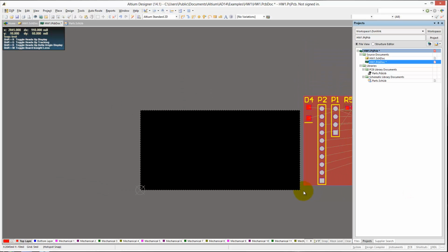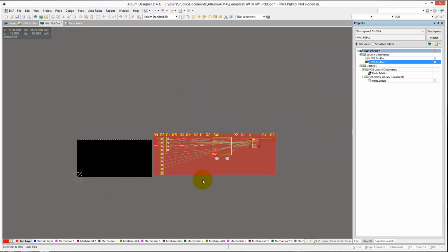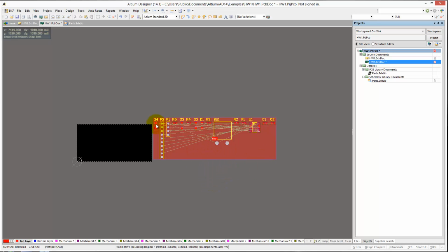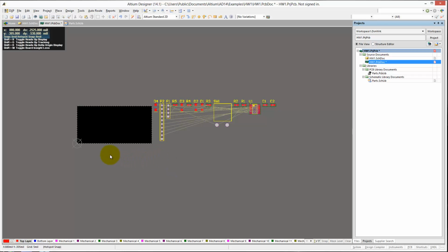and as you can see here on the right hand side now, these are all the components and pads that we have done. And this is the first time where you can see the different sizes of the different components. If you look at the switch, it's actually an extremely large switch that we chose here compared to even our microcontroller. And the pinout header is also fairly large. This red thing around here is a room definition, and you can find a tutorial on how to use rooms properly. In our case, we just delete this room for right now because we have no need for it.